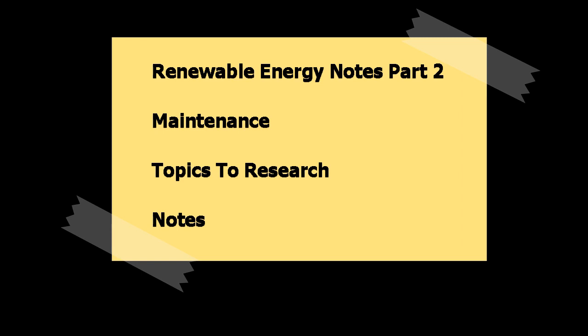Going over some tests that you need to do when you have a solar system or when you're installing a solar system. There's 3 tests that I'm just going to list that you may need to look up in your spare time, just to make yourself more familiarized with the terminologies and what they mean. Here we are with the first one, continuity test, and that is to make sure that there's no breakages in the wires. Then polarity test and insulation resistance test.